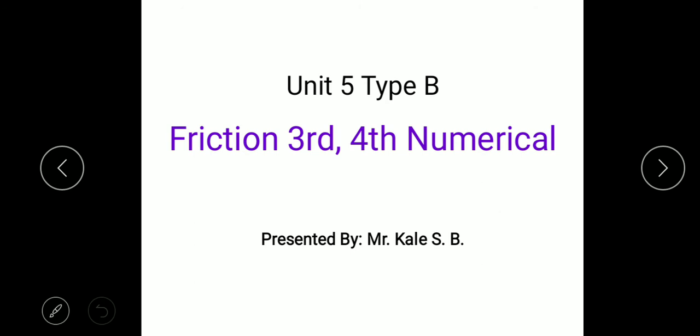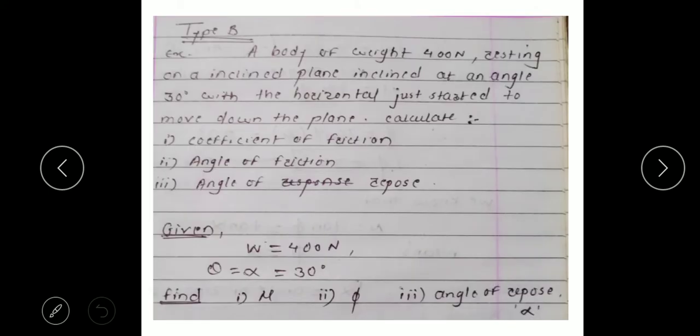Coming directly to the numerical. This is a type B related numerical. A body of weight 400 Newton is resting on an inclined plane. So here the body is placed on an inclined plane, which means it is related to type B. It is at an angle of 30 degrees, which is the value of theta or alpha, with the horizontal, and it has just started to move down the plane. We need to calculate the coefficient of friction, angle of friction, and the angle of repose.